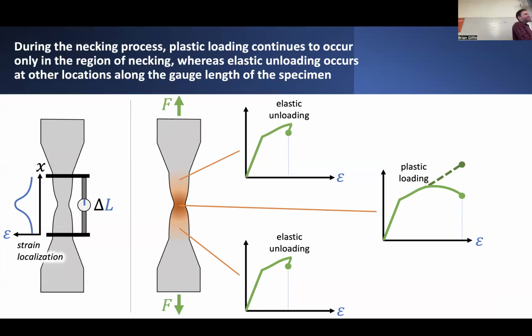But that's very dangerous. In general, if you're calibrating models for metals, you want to make sure that the actual material calibration is always exhibiting strain hardening behavior, not strain softening. Because, again, you could make the mistake of conflating nonlinear material behavior for what is effectively a nonlinear geometric effect.